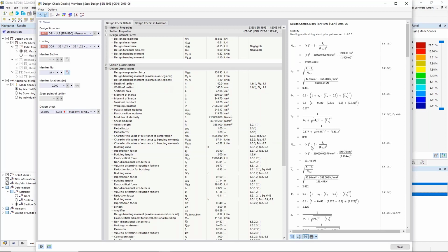And as we can see, we said, okay, we want to specify the buckling length around the Z axis in a way that we get the critical load correctly also in the design check. So we used the 7.7 meters. And basically it calculated now the critical load of 190 kilonewton.